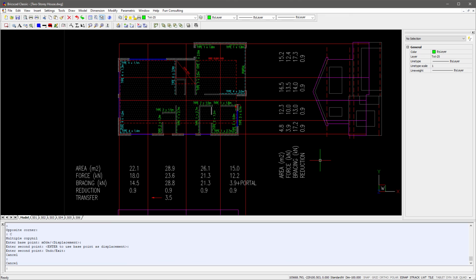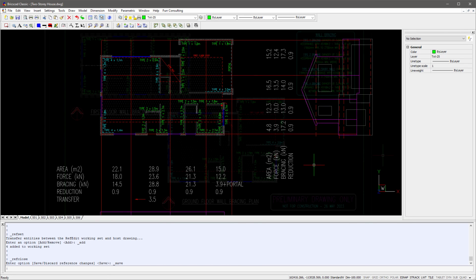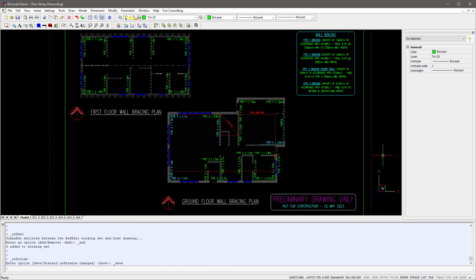What we might do now is have another look at the overall bracing and perhaps add a few other areas to ensure an even distribution. In our case, we've now added an additional short type 2 and 3 braces on the north and south face of the lower level. With the bracing layouts in a block, we can transfer them to our drawings. At this point, we might tidy up the bracing drawing page, such as adding a note that specifies the need for additional hold down for type 4. This way it will be clear to the builder.